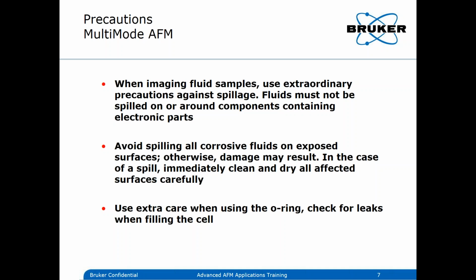By the way, for the multi-mode, you have scanners which are liquid resistant, and when you buy them, they have a 3-year warranty against leakages if your droplet would go in. They have a rubber sealing. The standard scanners do not have that. In any case, I would also recommend using something like parafilm to shield off the top surface as well.